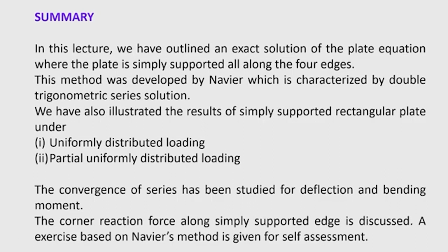Only the first term gives reasonably accurate results. The corner reaction force along the simply supported edge is also discussed, and lastly an exercise, a self assessment problem based on Navier's method, is given for solution. So, you can solve the problem and compare the results with the results that have been given in the slides.